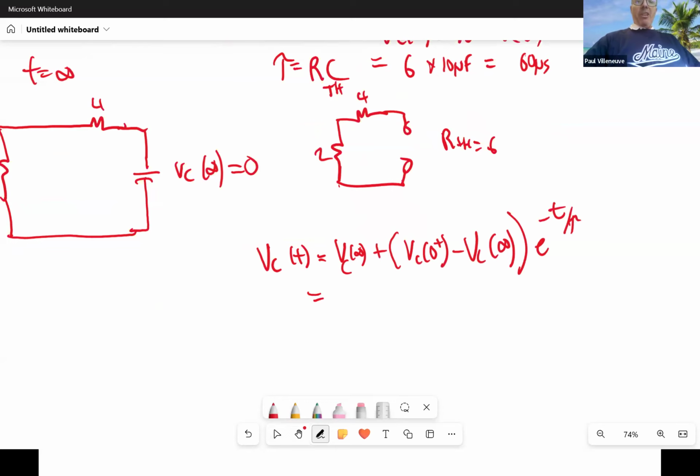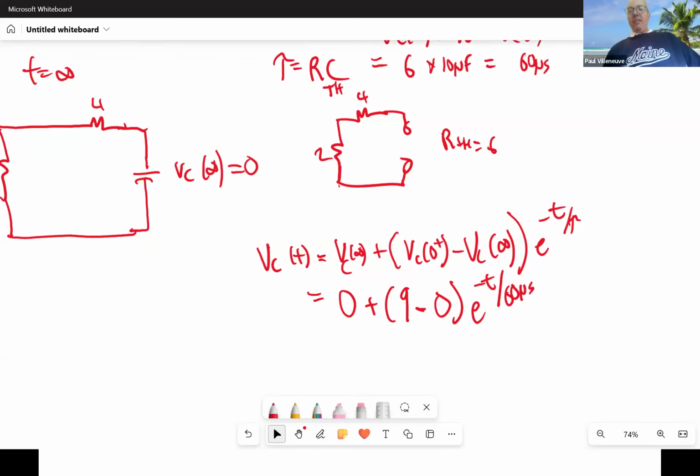Now I'm going to plug in my results. 0, plus 9 minus 0, e to the minus t over 60 microseconds. So my final expression is 9 e to the minus t divided by 60 microseconds. Okay? Questions on that? Make sense? Don't make sense?